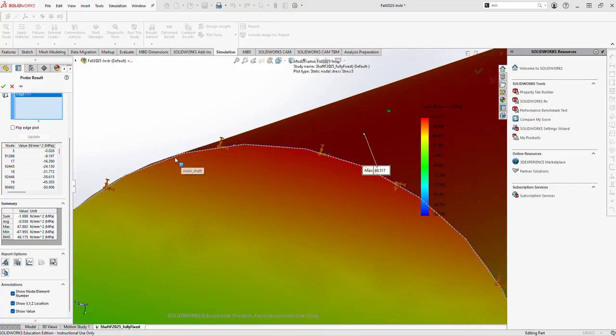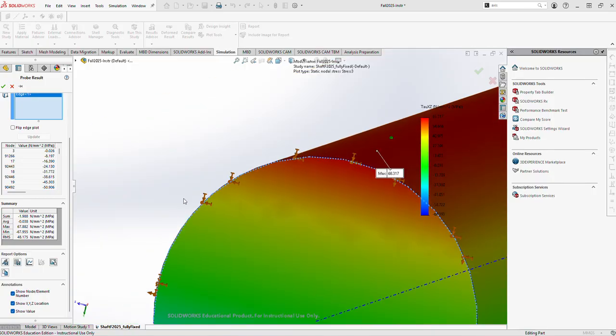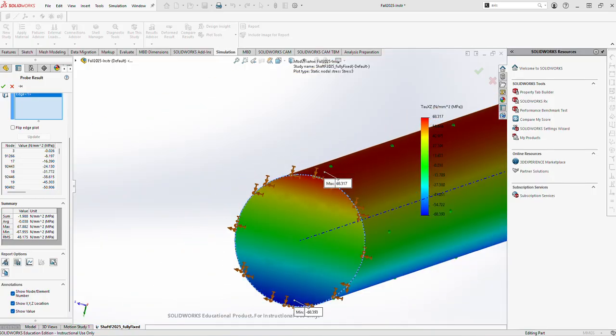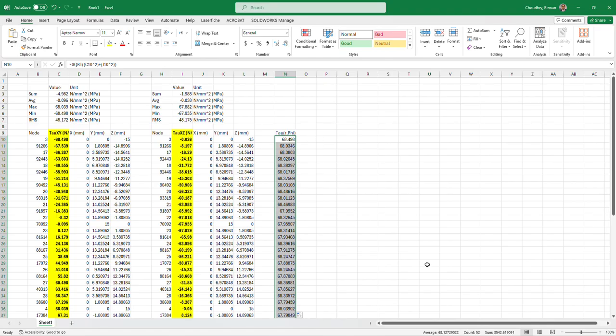If you look closely, this is the edge location, so the contour is not perfectly circular for our element. There will be some small differences in the radial location for this edge based on the mesh size that we have chosen, and that gives rise to these small variations in the value that we are calculating.